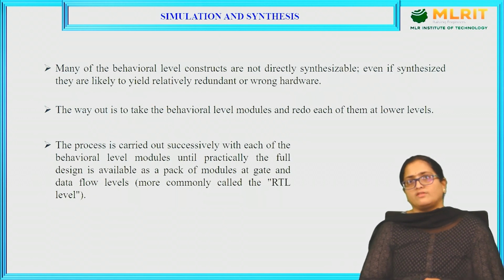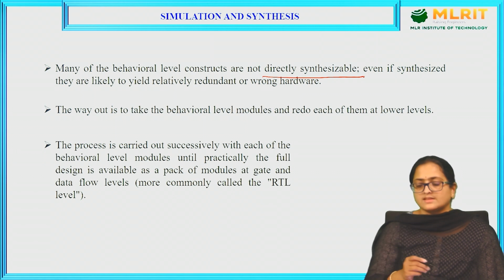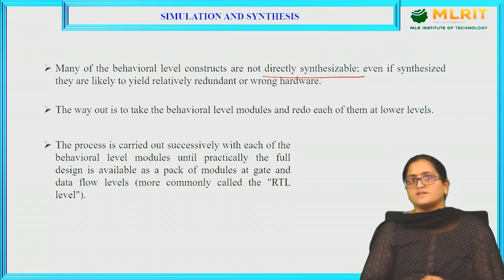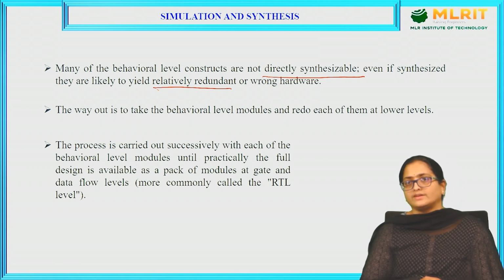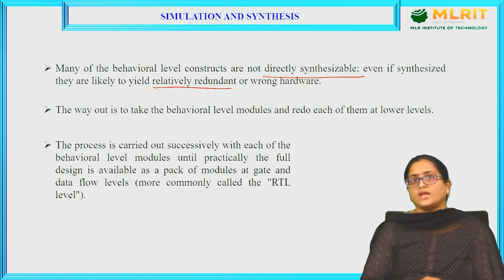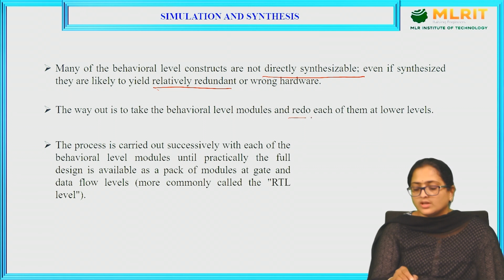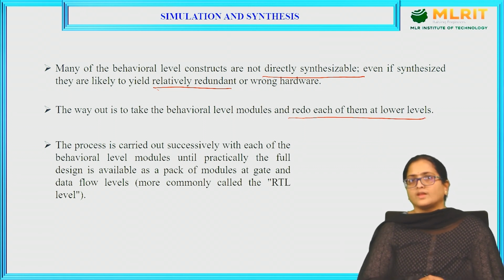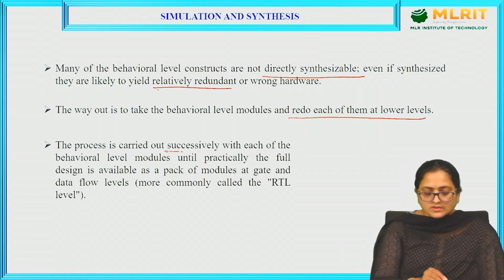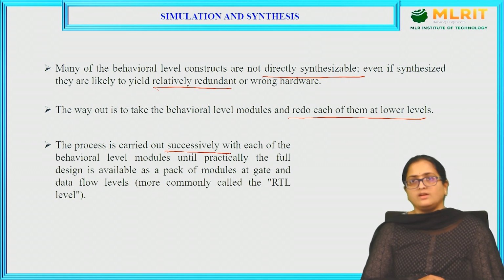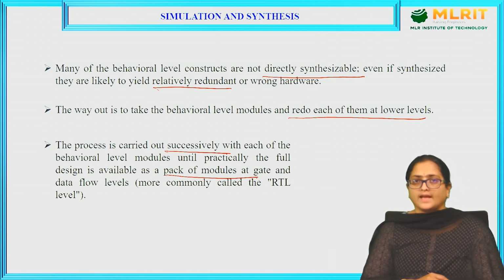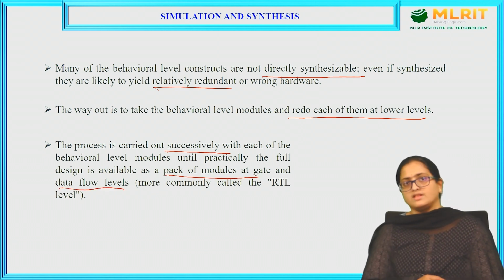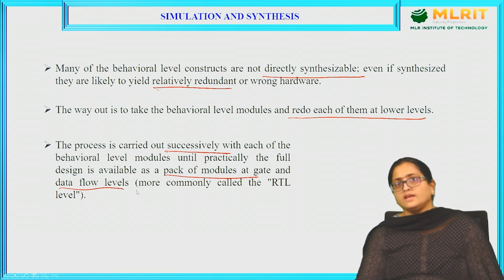Many of the behavioral level constructs are not directly synthesizable. Even if synthesized, they are likely to yield relatively redundant or wrong hardware. The way out is to take a behavioral level module and redo each of them at a lower level. The process is carried out successively with each behavioral level module until practically the full design is available as a pack of modules at gate and data flow levels, which is called the RTL level.